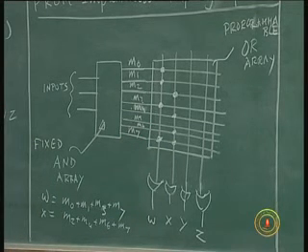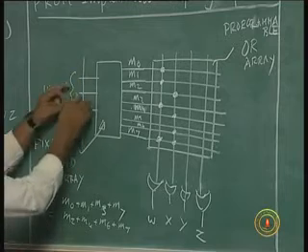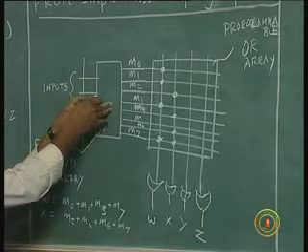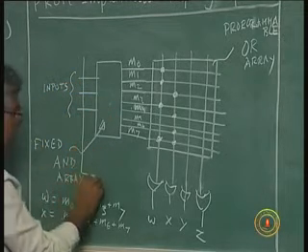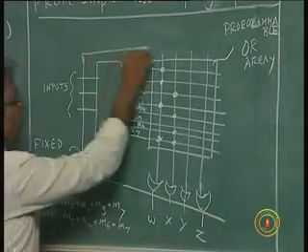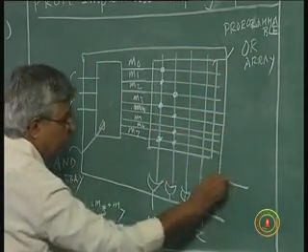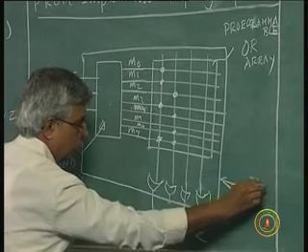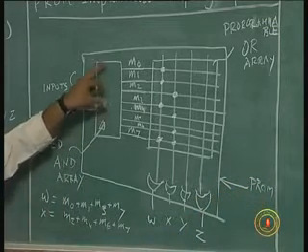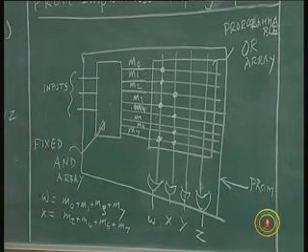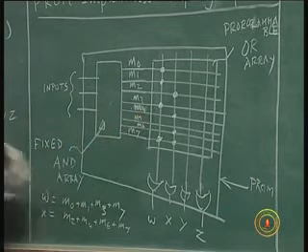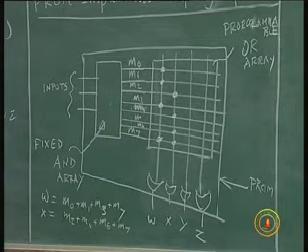Now the programmable device comes into the picture. This is a programmable device. This total device, where these are my inputs available, I don't have any control over what is inside here. And up to this is a PROM, in which a fixed AND gate will produce all the minterms required, and a programmable OR array in which I can retain those minterms required for each of these outputs and not connect those inputs which are not required for that particular output.